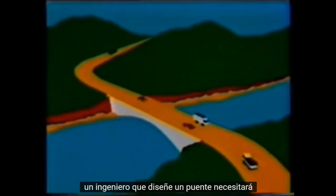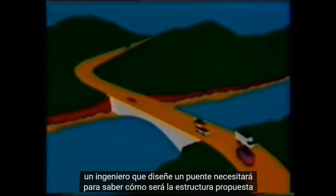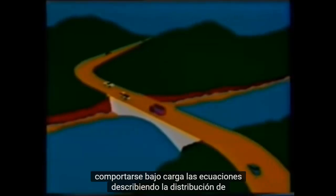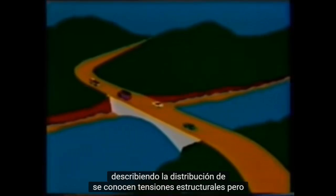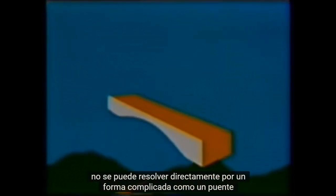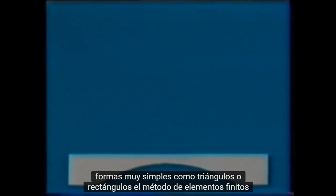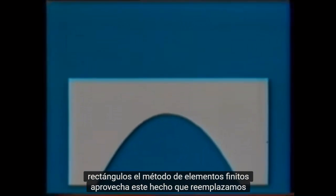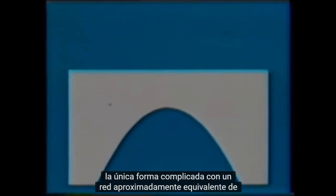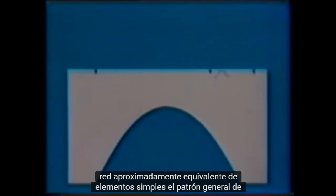An engineer designing a bridge will need to know how the proposed structure will behave under load. The equations describing the distribution of structural stresses are known, but they can't be directly solved for a complicated shape such as a bridge. However, the equations can be solved for very simple shapes like triangles or rectangles. The finite element method takes advantage of this fact. We replace the single complicated shape with an approximately equivalent network of simple elements.